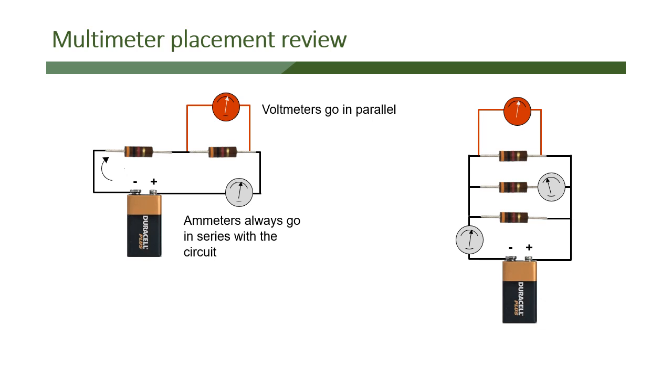They have their own paths back to the battery, and therefore we can measure the total current in the circuit by breaking the circuit near the battery, and then we can see all the current moving through the circuit. Or if we want to see the current going through one node of this network, one load of this network, we just open up the circuit where that one load is and put the meter in, and we can measure the current through that node of the circuit, or for that load. So those are 2 ways we can measure current in this kind of parallel circuit.